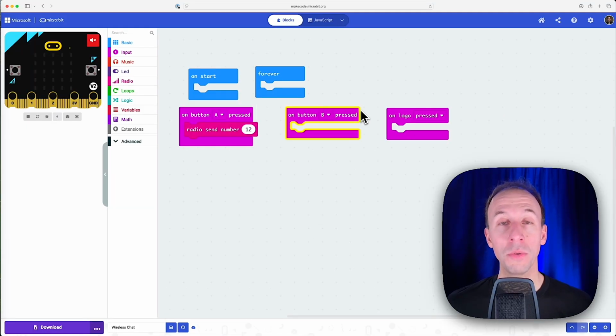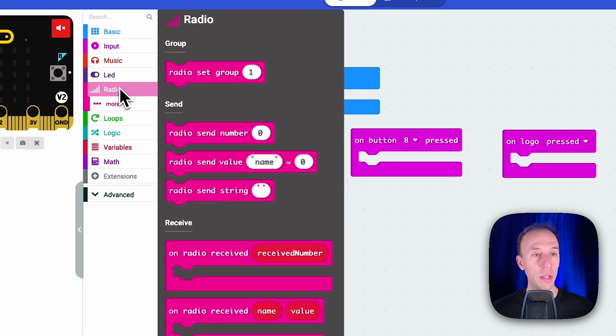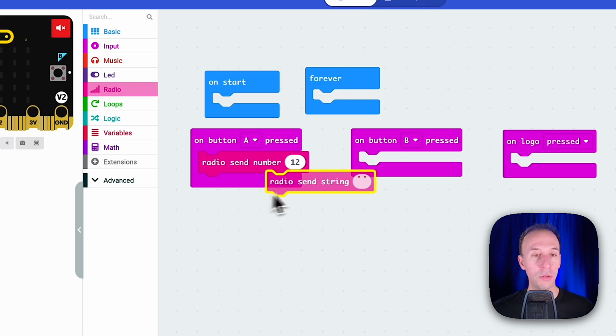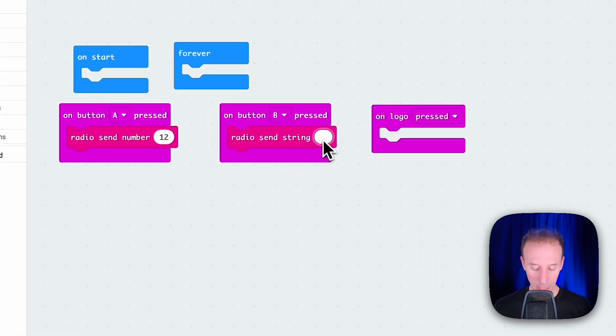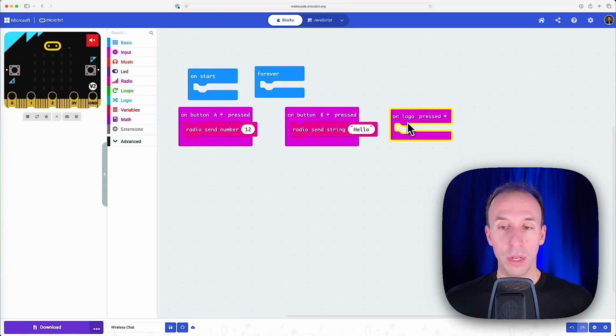When B is pressed, we want to send a string. So let's go into radio and grab radio send string, put that in there, and you can type any message you want into there. So I'm just going to put hello. We're going to wait to do the logo pressed in a minute. I want to set up these two first.